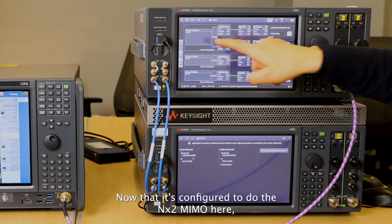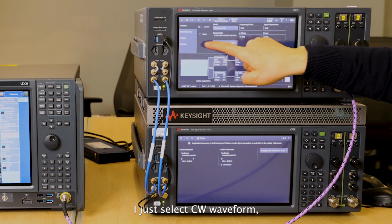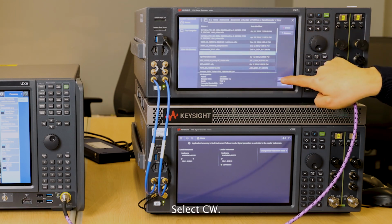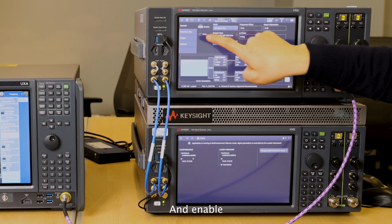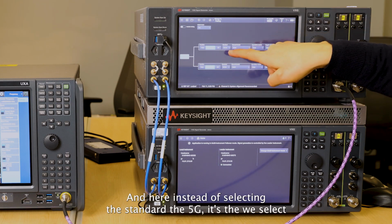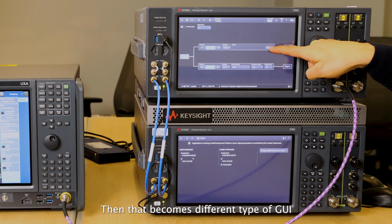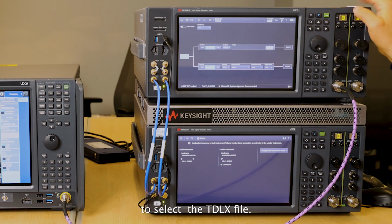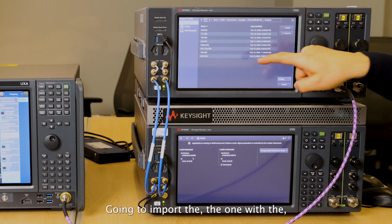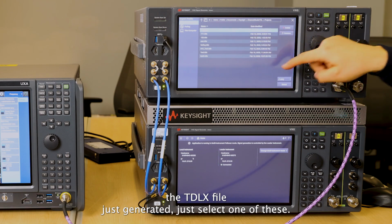Okay, now that it's configured to do the N/2 MIMO here, I just select the CW waveform, select the CW, and enable and press fader box. And here, instead of selecting the standard as 5G, we select the custom. Then that becomes a different type of GUI to select the TDX file. So now we are going to import one of the TDX files just generated. Just select one of these.